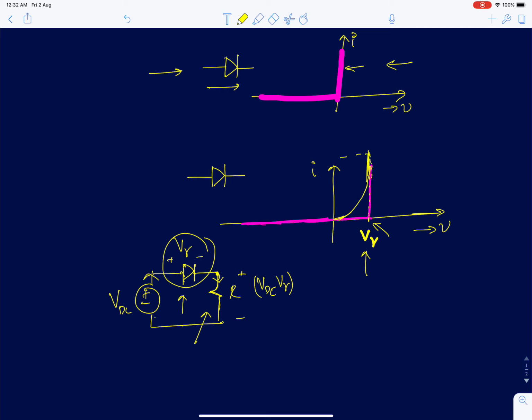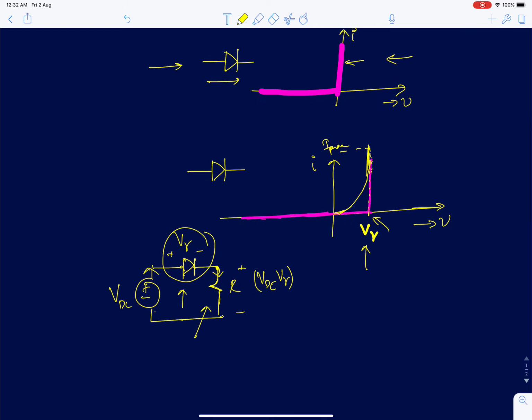So we'll have to see what is the peak current or the max current that you're going to operate. From that graph, you can find the value of V gamma, and we said that it will vary if your currents vary. For example, if the Imax is 10 times or 20 times or 100 times higher, then V gamma will not have a proportionally larger change, but only small changes. So we discussed how to model the diode as a voltage source.